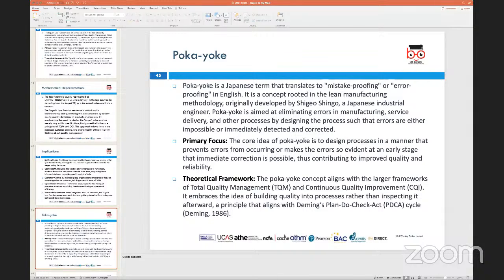Somebody is sewing in the sole, somebody is sewing in the top of the shoe, somebody is pasting the sole, and some of them are installing the inners of the shoe. Now all of this is being done by different machinery. So here the poka-yoke method looks at individual processes in the manufacturing of the finished product, and what they will try to do is make it easier for operators to perform their task correctly.